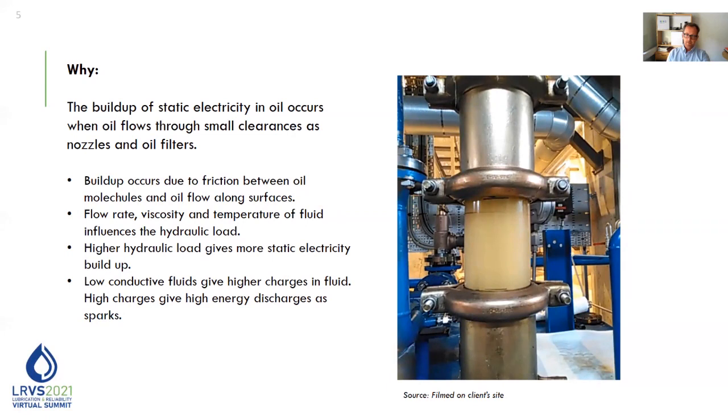As you saw on that film, you saw those discharges, and of course this breaks down a lot of oil into varnish, and this varnish ends up on the cold places such as the oil coolers, and it gets stuck in the bearings as varnish as well, and causes a lot of problems.